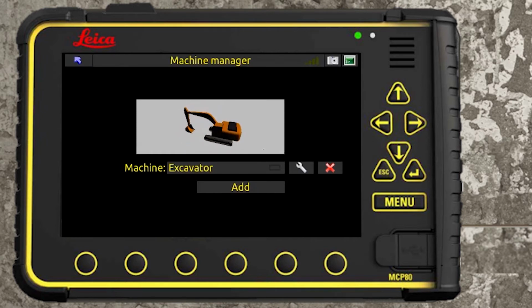Down below here, you'll see a tab. It's not showing me on the simulator, but you'll have it on your panel. It'll say 2D settings. You can either store or load your settings. Basically, the settings on your panel at the moment are from the previous machine that you were working on yesterday. So you just need to select the load button.